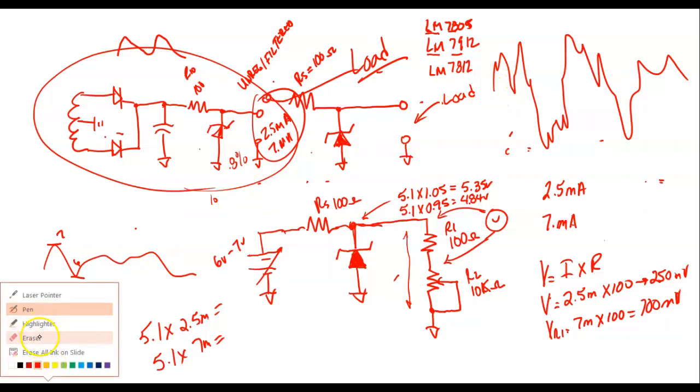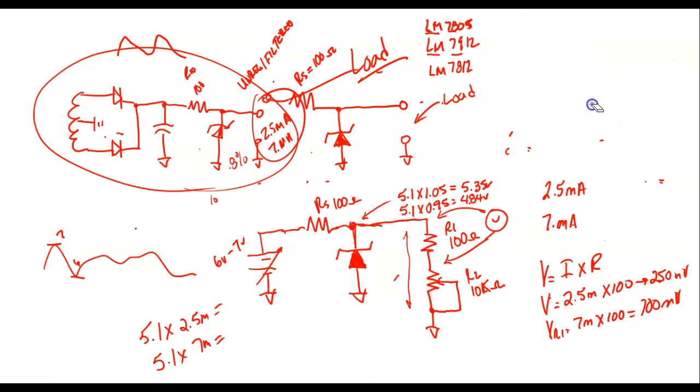And we're using an LM317, which is a variable regulator, which is really neat. So all these connect like this. We come over here, we have our 3-terminal regulator, usually drawn as a block. We have a common, we have unregulated filtered in, and we have regulated out.